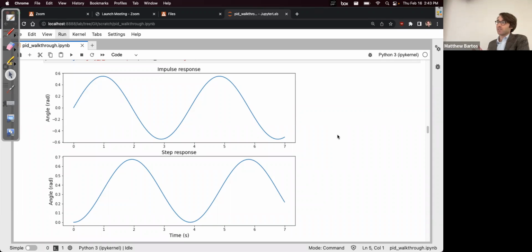So in shorthand, proportional control essentially adds springiness to your system. It's pushing back in direct proportion to your deviation from some reference. So as the deviation from the reference angle increases, the proportional controller will push back in direct proportion, which will cause it to move back towards the left, where eventually it will get another force pushing it back in the opposite direction. And so you'll end up with a system that is constantly oscillating back and forth.